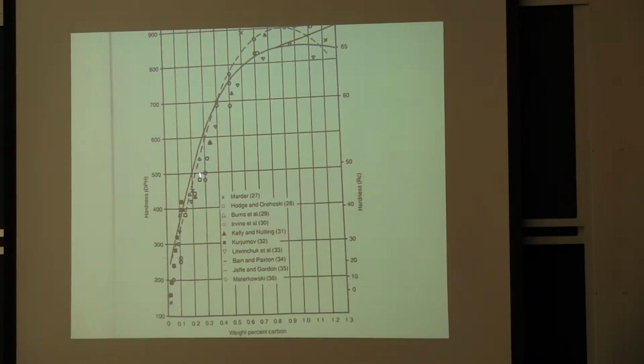Medium carbon steels are intermediate, and the high carbon steels, this is why we talk about high carbon steels as high hardness, medium as intermediate, and low carbon as low hardness, merely a function of the carbon content. But the depth of the hardening, how deep I can do that when I quench it, is a function of the alloy content. So if I need to understand whether I can weld a steel, I don't want to get something that's too hard.